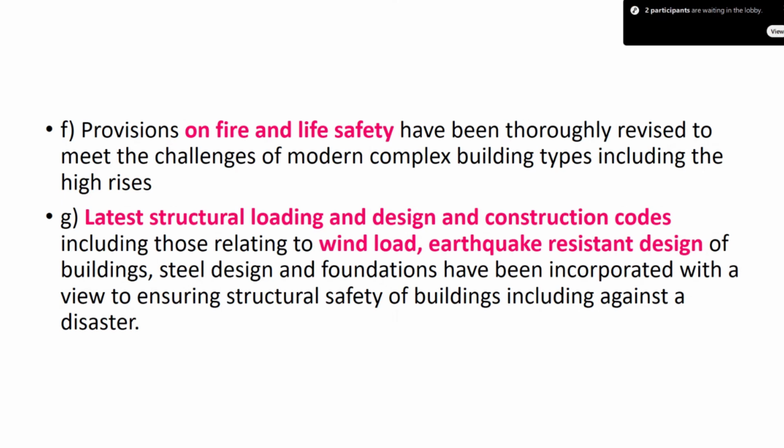Clause 13.9.1, again page 123, specifies that aluminum and aluminum alloy conduits and accessories should not be used where frictional contact with oxygen rich items such as rusty steel might occur and cause sparking.